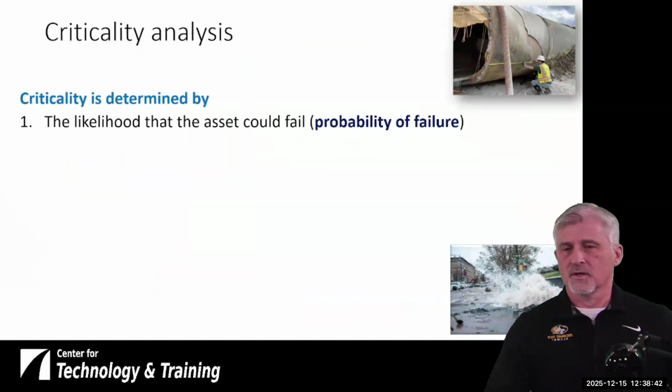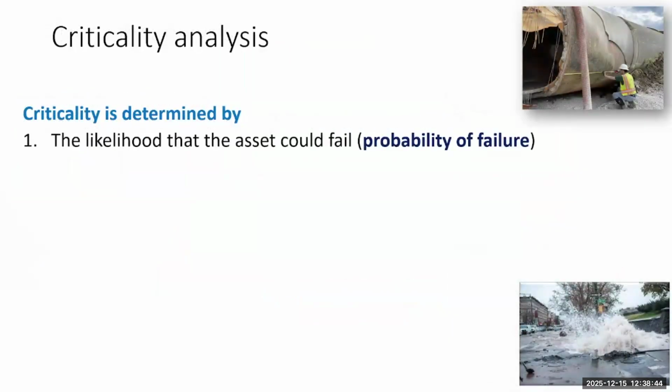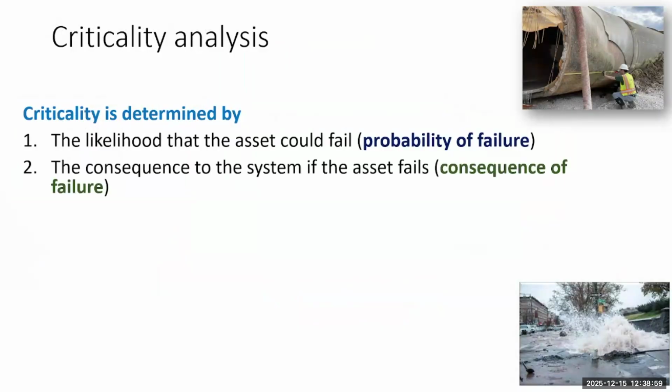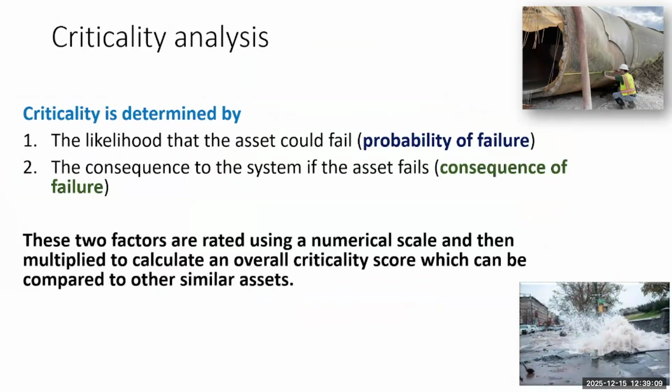Criticality analysis. What's criticality determined by? We need to look at what are the chances that this asset could fail? What's the probability of failure? So POF is something that we'll talk about. And then what's the consequence? What's the result of that failure? So, what are the chances, and then what would happen if it fails?